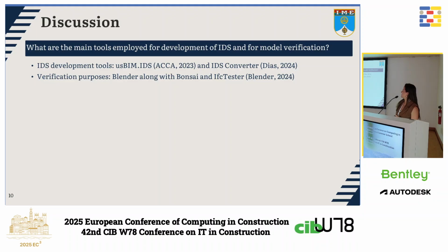About the main tools employed, for IDS development, the most cited tools were usBIM.IDS and IDS Converter. And for verification, the most frequently cited were Blender with the Bonsai add-on and IfcTester, due to their ability to read both IFC and IDS files and perform compliance checks.